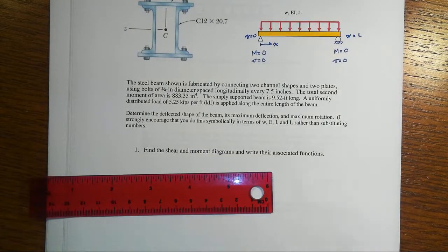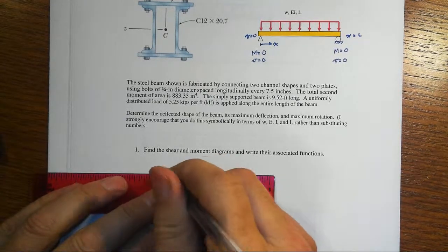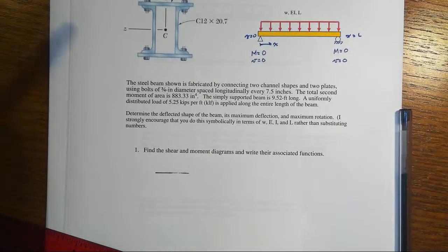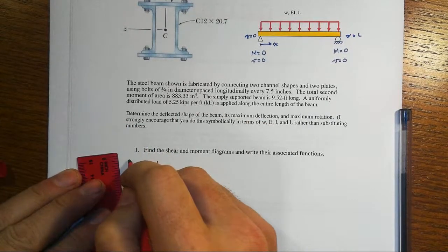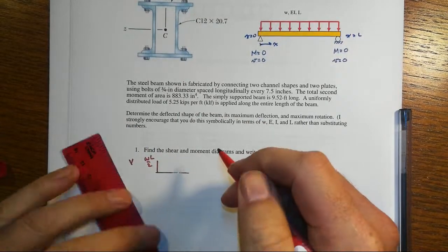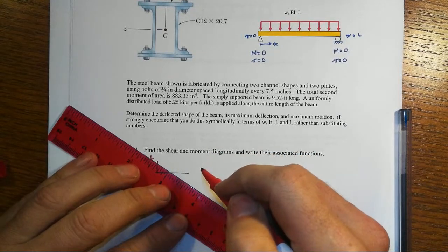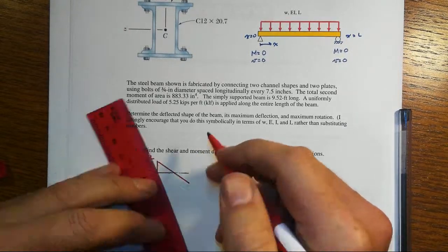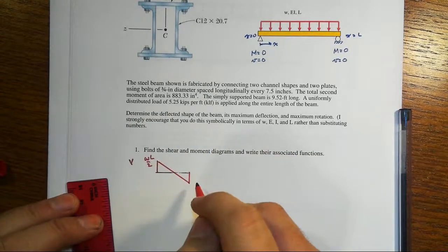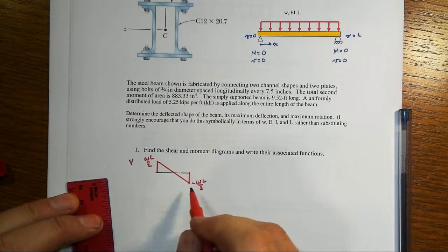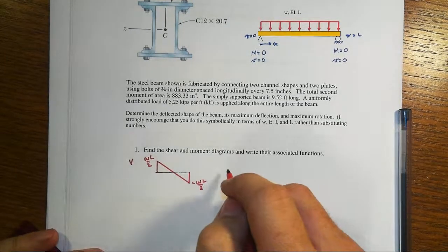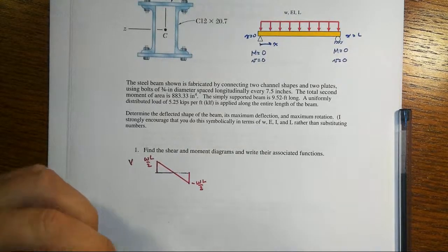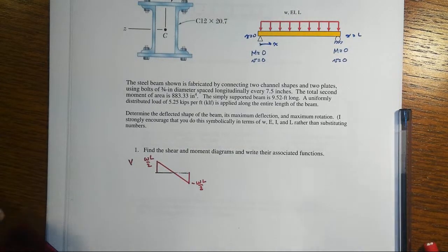Now, we know, without having to dawdle around with this too much, exactly what's going to happen here. The shear diagram is going to go up by the reaction at the left, so that'll be WL over 2, W being positive downwards now, and then the reaction at the right will also be upwards at WL over 2, so the shear goes to minus WL over 2, and we've got this little guy. Well, wait a minute, we have to somehow find a way to get the shear function out of all that.